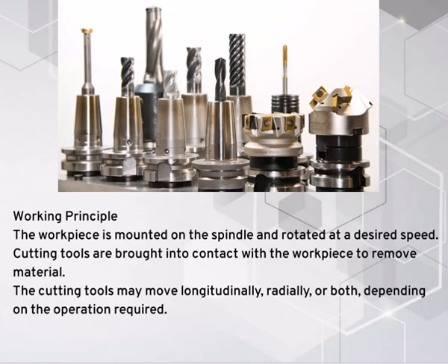The working principle of a lathe machine: the workpiece is mounted on the spindle and rotates at a desired speed. Cutting tools are brought into contact with the workpiece to remove material. The cutting tools may move longitudinally, radially, or both, depending on the operation required on the lathe.